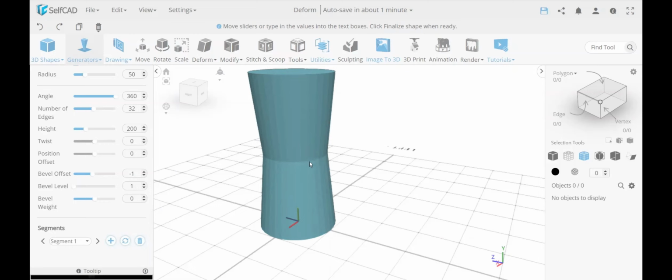So the bevel itself is making it shorter, smaller over here, or with a positive bevel, it goes the opposite way, bigger. The next thing is the level. Once I add a level of 2, you see we no longer have the center that I created over here. It's split into 2, and adds another segment. And if I keep on adding segments, as you can see, it becomes smoother and smoother and smoother by adding additional segments and so on.